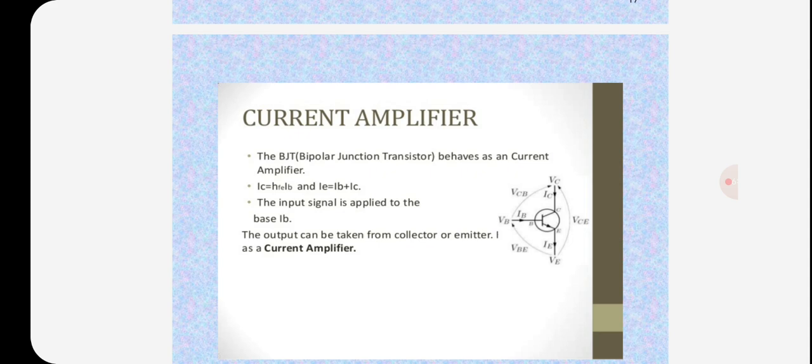So a transistor acts as an amplifier by raising the strength of a weak signal. The DC bias voltage applied to the emitter base junction makes it remain in forward biased condition. This forward bias is maintained regardless of the polarity of the signal.